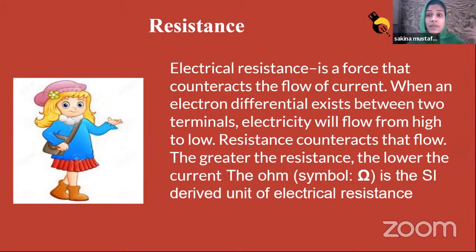Now you have seen there was 915 milliampere, while my LED required just 20 milliampere. The current was passing approximately 5 times more. So I have to provide some knob, some resistance, so that the maximum current should not flow and my LED should not get damaged. So the resistance is there.